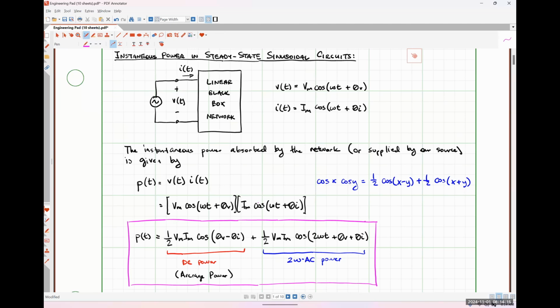So effectively, a couple of things that we can unpack there, right? First, since we're only interested in magnitudes and phase angles, even though this is a time domain quantity, our analysis is still going to be in the frequency domain. We're just going to take the parts of our phasors that we need and plug them into this equation, okay? So you should never, ever get imaginary numbers when you're using this thing. If you are, you're doing it wrong. We literally just take the magnitude, take the phase angles, and plug them in where the equation tells us to do so, okay?